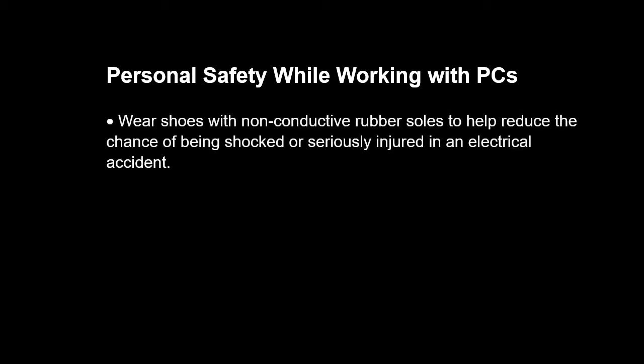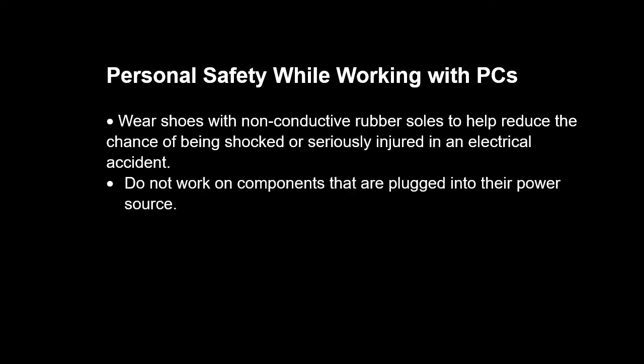Now let's proceed with personal safety while working with PCs, or personal computers. Wear shoes with non-conductive rubber soles to help reduce the chance of being shocked or seriously injured in an electrical accident. As we all know, rubber soles on our shoes are non-conductive of electricity. Do not work on components that are plugged into the power source. Also apply common sense every time you work with PCs.